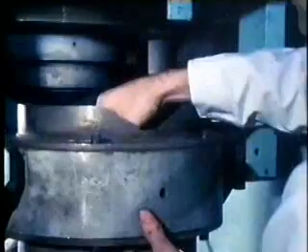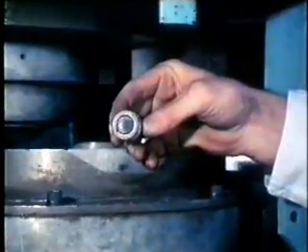What emerges is a hard slug of metal with some diamonds dispersed in the middle. These slugs have to be processed in large vats of acid. The acid dissolves the metal alloy and leaves fine sand-like particles of diamond, which form the basis of the cutting tool. The basic structure is a laminate one with a dense layer of polycrystalline diamond bonded to a tungsten carbide base. The tips can be either clamped or, as in this case, brazed to the shank.